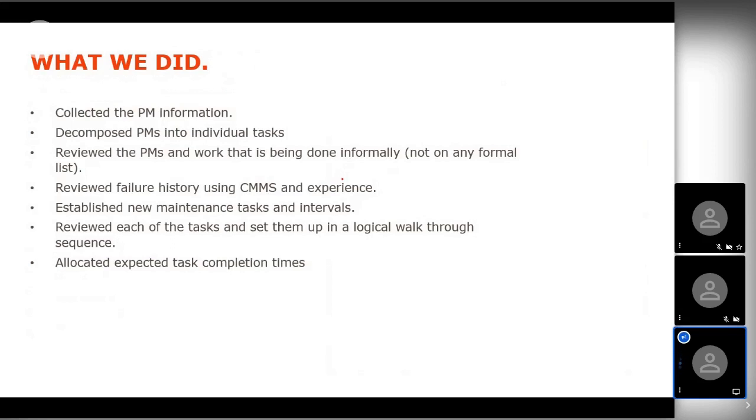The most important part is to have the right people. The maintenance engineer or the reliability engineer on their own cannot do this by themselves and have a good strategy. You must include the maintenance technicians, the operators, the original equipment manufacturers if you can, supervisors, as many people as you can. So we sat down in a room, one production line, we sat down for 1 full week in a room. If you've ever tried to get maintenance and operators in a room doing paperwork for a week, you'll know how hard that might sound. Review every task. Come up with a new strategy for each individual piece of equipment based on the consequence of the failure and put it all together.